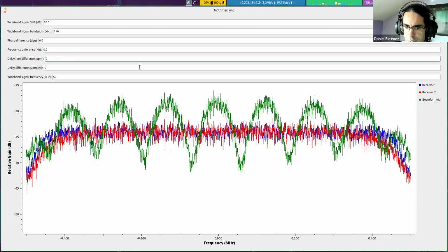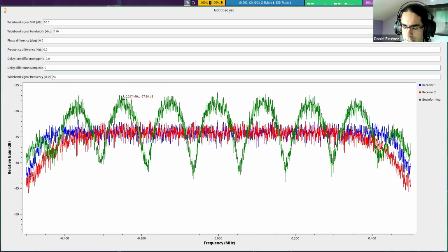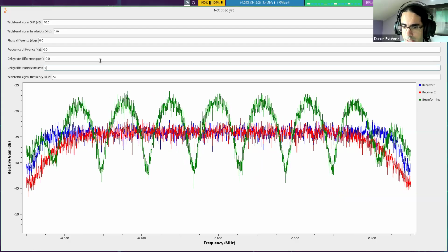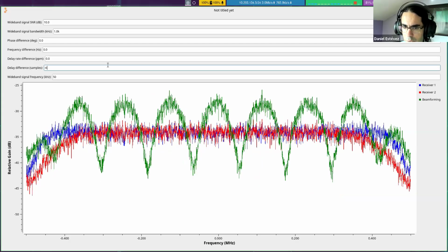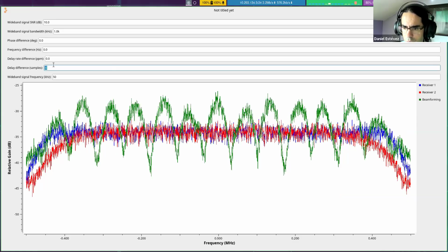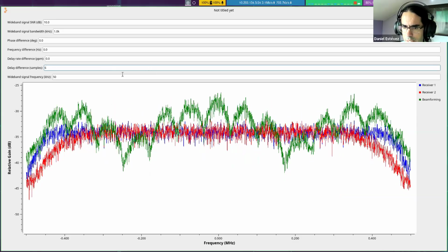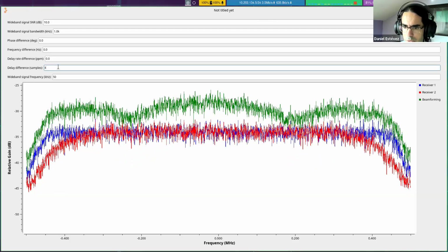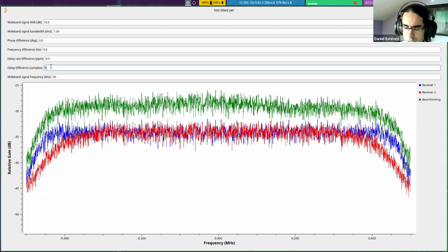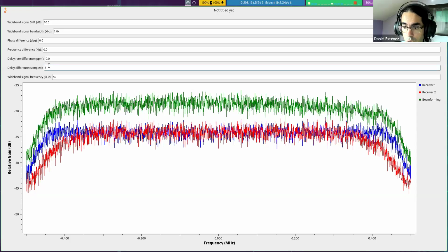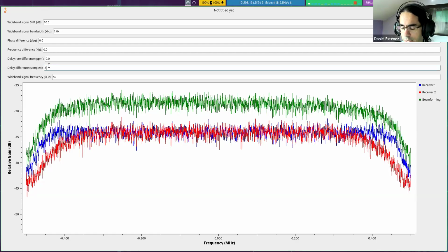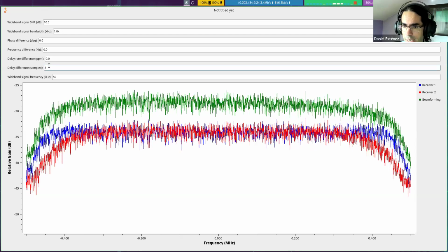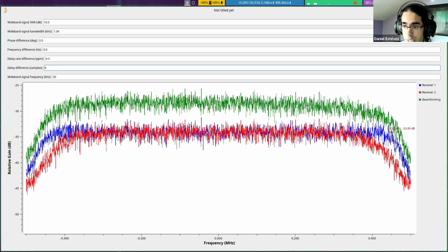And I can stop this, but because they have accumulated, the delay is like that. It's accumulated. If I wanted to compensate this, I would need to place, I don't know what's the right sign. Maybe it's positive. If I play with these numbers and choose the right delay, maybe it's about 8 samples, I can cancel it out. So this gives you a hint about how in real life we can cancel out these effects to align the two signals and achieve this beamforming combination properly.